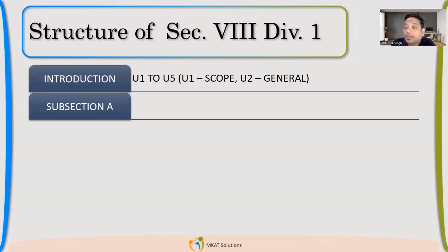Design codes are the codes which give requirements for a particular kind of equipment, like section 1 talks about power boilers. Section 8 division 1 covers all kinds of unfired pressure vessels, right? Section 3 is for nuclear. So there are different categories. These design codes are made, and there are some subsections like section 2, section 5, section 9. These are supplementary. They will be required in each and every design code. I hope you got that point.